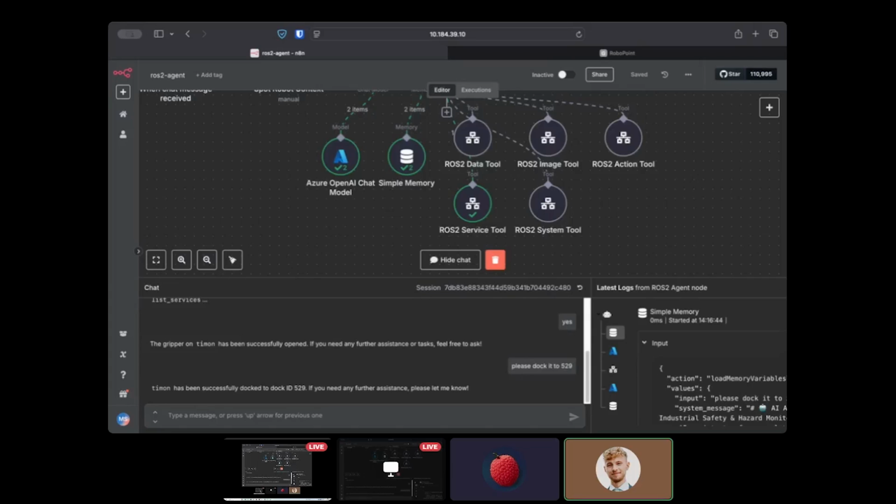So that's why you need, for example, 2D information from the VLM or from the model or from a CNN also. You need 2D information, where the object is, and then you can use this 2D information with your camera intrinsics to convert it into 3D space. And with this information, you can then use, for example, IK solvers like MoveIt or vendor-dependent IK solvers to do the actual grasping or motion planning.